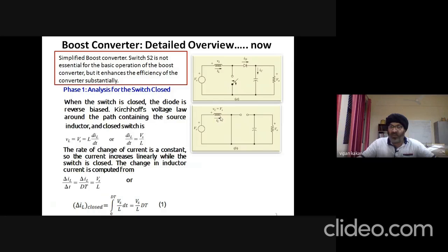And we know that the voltage across this inductor, because when this switch is on, this voltage is now connected with this inductor having the closed path, and now the current starts to follow this loop. And we know that the rate of change of current in the inductor gives us the voltage across that inductor, which will be equal to the supply voltage over here.